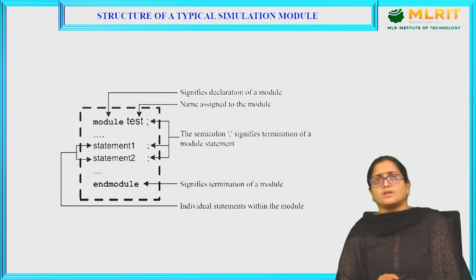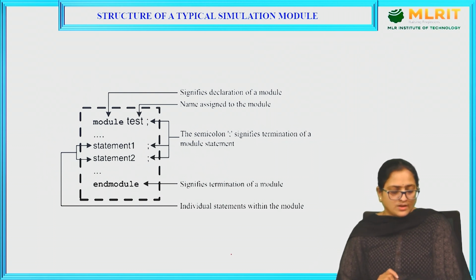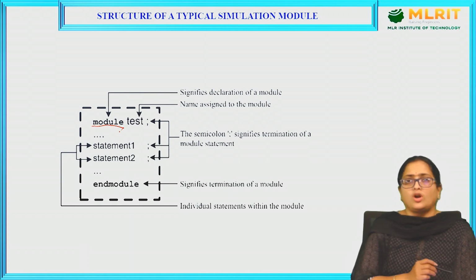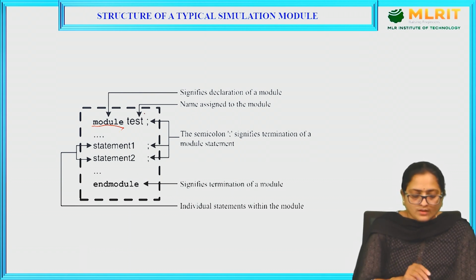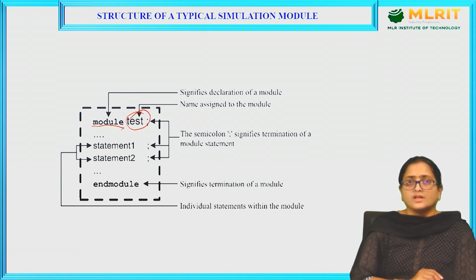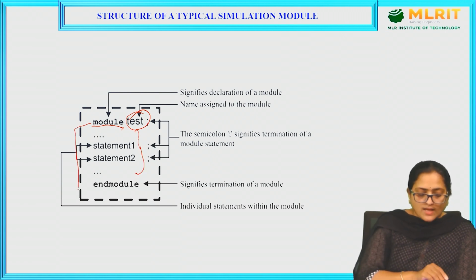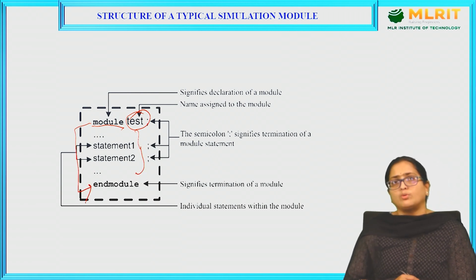Structure of a typical simulation module. Your Verilog code first starts with the keyword called module, given with the module name. Then you can write n number of statements, and this module has to end with the keyword called endmodule.